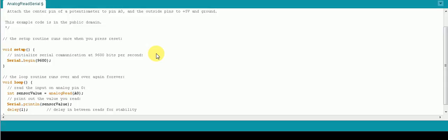Now let us understand why we need an ADC at all, when all the things that we use in daily lives are digital in nature. This is a very big misconception in our understanding. Analog data is the most common form of data that is used in instrumentation, measurement, or any control appliances. So it has to be converted to digital data to be understood by the microcontroller or any other measuring device. So there we need an ADC. Now Arduino has a 10-bit ADC, which means that there are 2 to the power 10 values, that is the accuracy that you can get in this ADC.